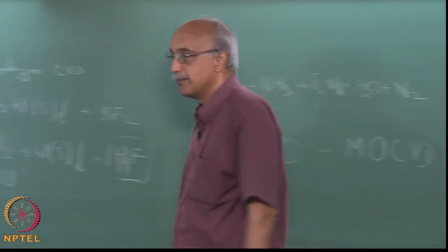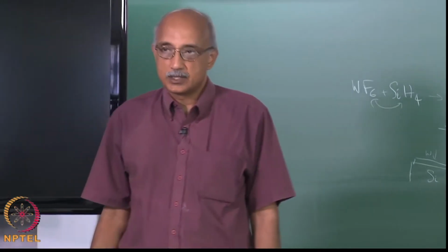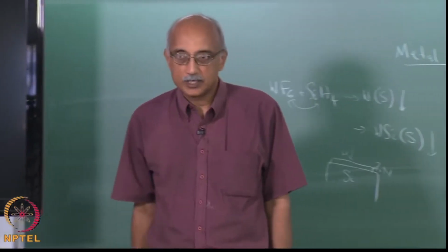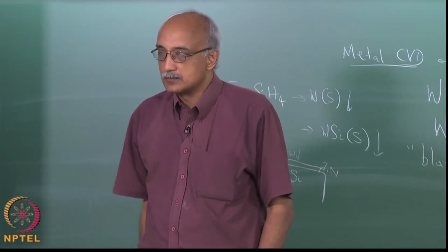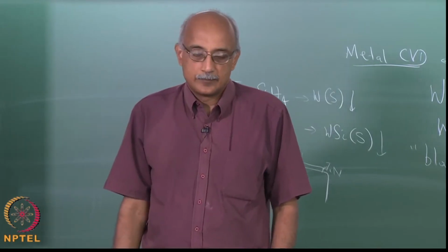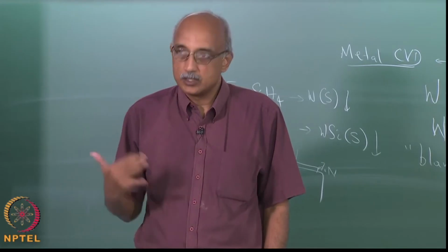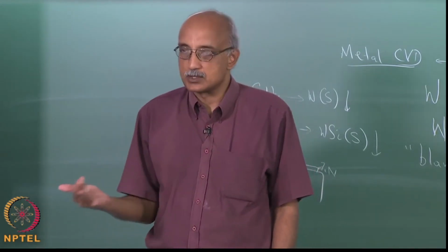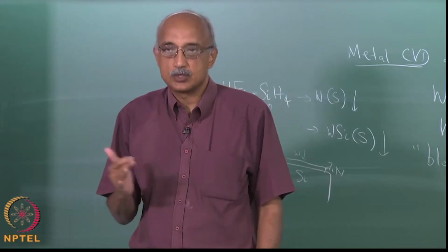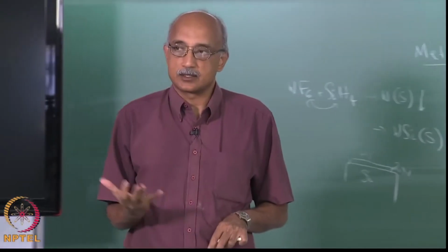Which stands for metal organic CVD. It basically just means that the vapor precursor from which you are depositing the film is organic in nature. And the reason you do this is again because there is no inorganic precursor. So, MOCVD in many ways is a last resort. You only do it if there is no appropriate inorganic species that you can use in your CVD reactor.